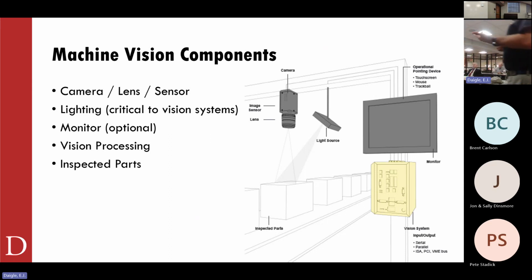I can remember one of the first ones I ever worked with that had the smarts inside. It was like its own little PLC. It had inputs, it had outputs, and the code I wrote based upon the vision sample determined what outputs turn on. I could trigger with an input, and then I could look at the part, say the part's good, and I could trigger an output and send that somewhere else. Could be an output that just turns on a red light or a green light. Could be an output that turns on a pneumatic cylinder to reject a part off of a conveyor belt. It could be a lot of different things that I look at along the way.